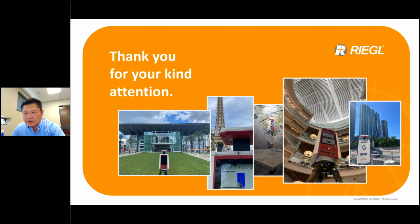I saw a question: can I use the TLS data to constrain MLS? Absolutely. We have customers that have our mobile system and also buy a terrestrial system for such an application. So if you're doing a corridor mapping of 100 miles, you can scan in certain strategic areas where you have high control.